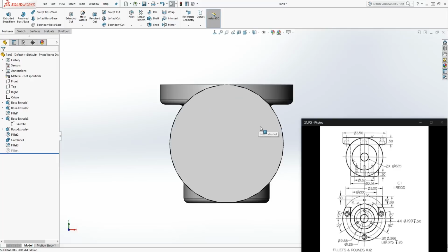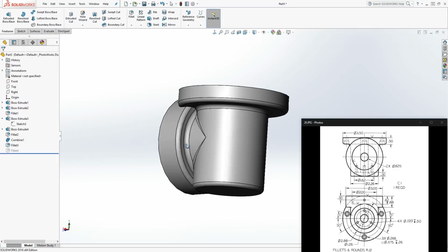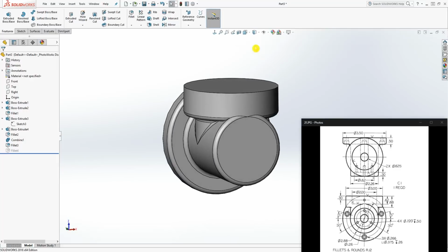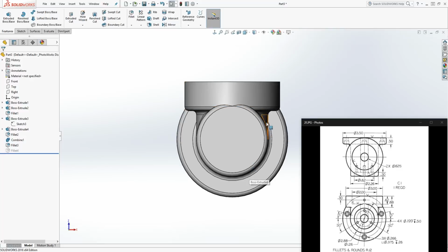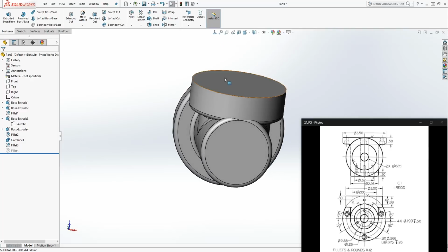So moving on. So we have the two main things done. So we have this feature. So if I go normal to, you see the two lines that I was telling you right here and this feature. Good. So what we need to do now is just start cutting our holes in it. And we're going to start from the bottom. We have the 1.62 and 0.3.